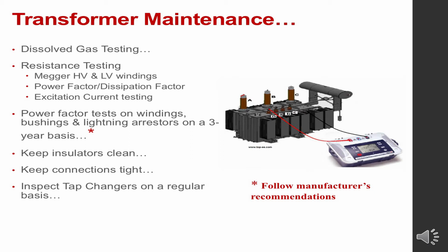And for those of you that do have load tap changers, of course, you'd want to spend some time inspecting those and testing those to make sure they're functioning properly, so that they don't produce a fault when they change taps on a transformer. Let's go ahead and go to the next slide.